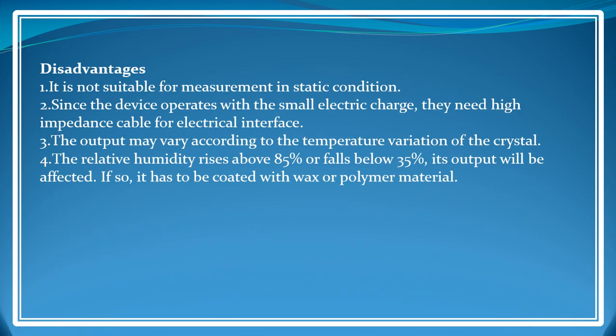It is not suitable for measurement in static condition, because as we talked about in the previous slide, it gives a very high frequency range. Since the device operates with a small electric charge, they need high impedance cable for electrical interface.